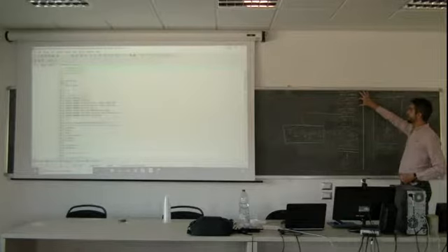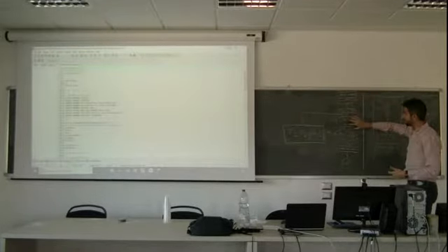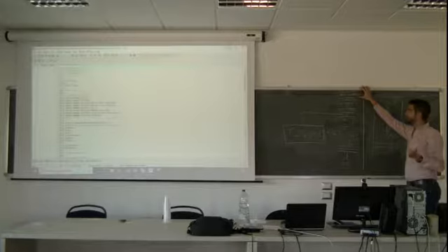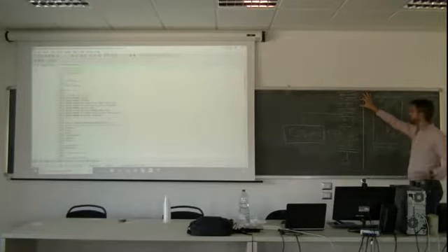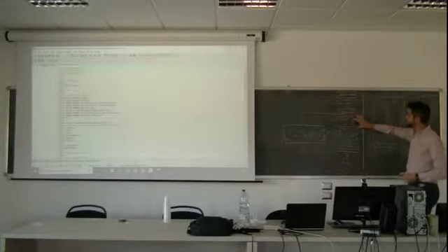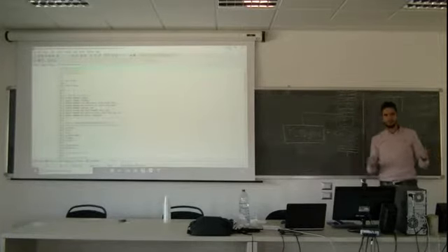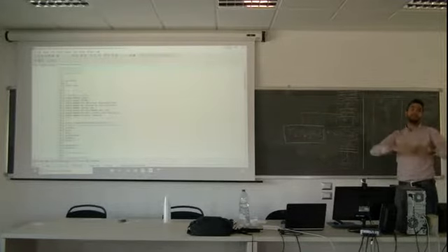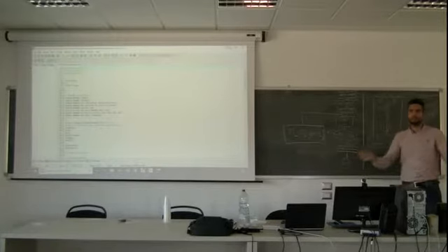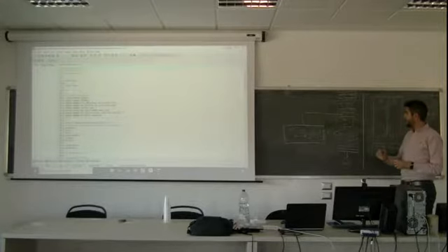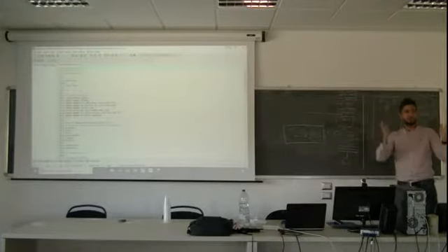I calculate the coefficients that I will need in the further equations, like areas, volumes, and positions of the nodes in the fin or in any domain. Then, before I start with the equations, I say, okay, I don't know the temperatures in all nodes, but I assume they are whatever, T0, 70 degrees, 50 degrees, 0 degrees, whatever you want to start with. And you apply the assumed map of temperature.